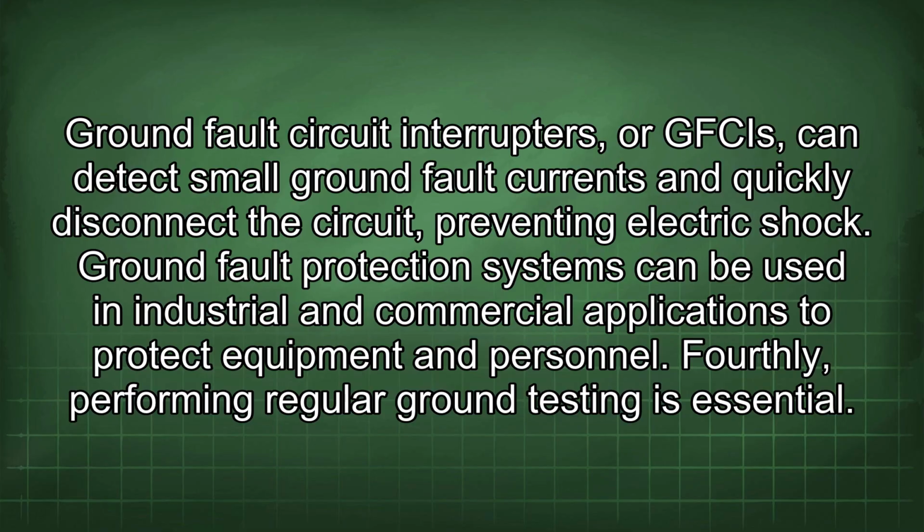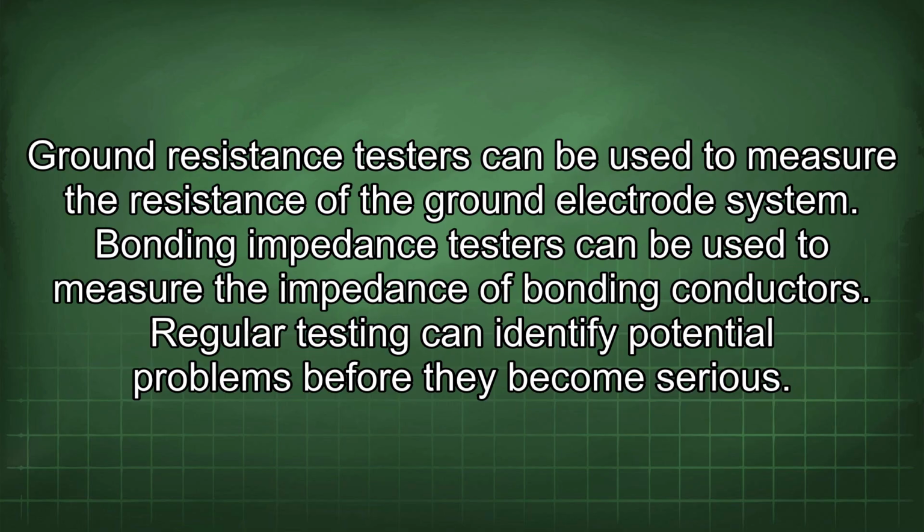Fourthly, performing regular ground testing is essential. Ground resistance testers can be used to measure the resistance of the ground electrode system. Bonding impedance testers can be used to measure the impedance of bonding conductors. Regular testing can identify potential problems before they become serious.